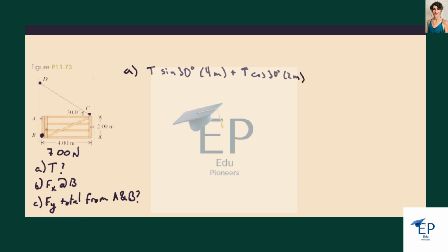That's because it has a moment that's 2 meters and the horizontal one has a moment that's 4 meters. And then minus the weight of the gate, which has a moment of 2 meters as well. And so this has to equal 0.